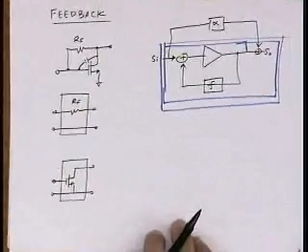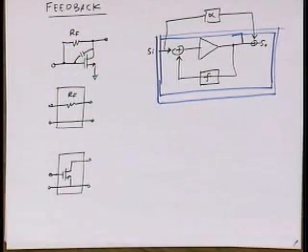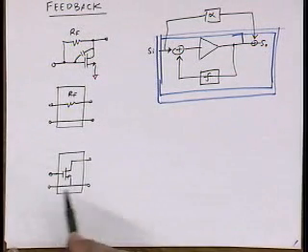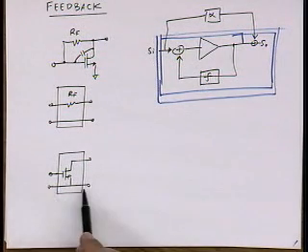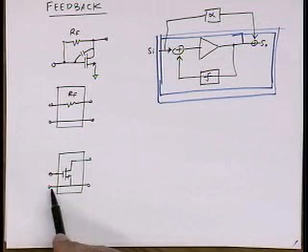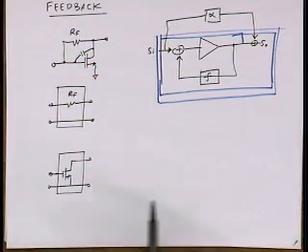One thing to watch out for is a transistor is actually a three-terminal element, right? So if we want it to be a two-port, we have to share a terminal. So here I'm sharing my source terminal. Obviously, that's how you get the different amplifier configurations. But the fact that this shared terminal is actually a short from the input to the output has some consequences, and we'll see that come up when we analyze some amplifiers.